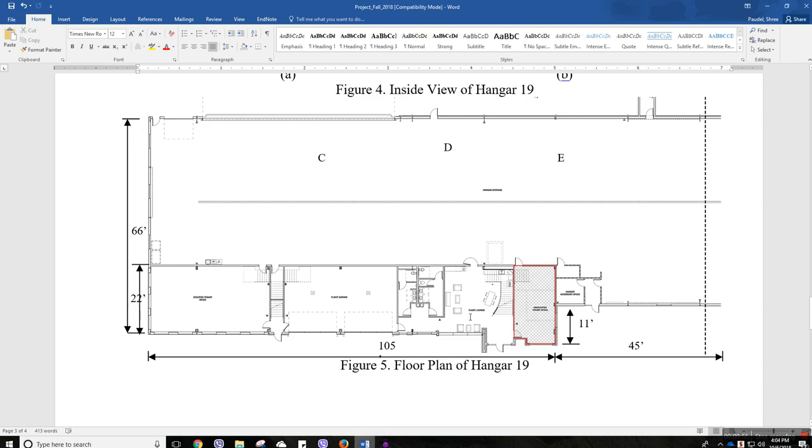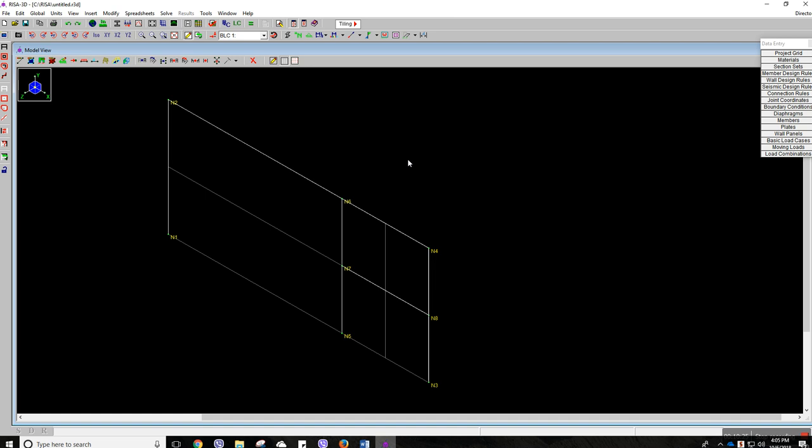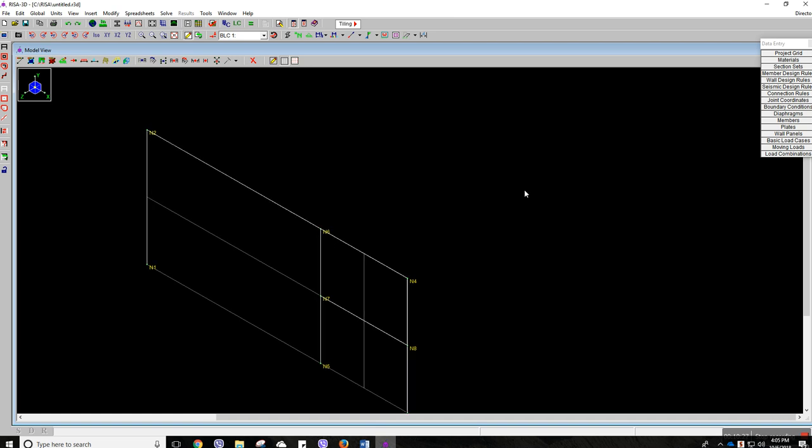So we are going to make the longitudinal axis here. Risa 3D has a very nice application on that one because we can just copy your structure to the other parts. So here, the span is 105 and there are 1, 2, 3, 4, 5 and 6. There are 6 spans, like there are the columns in the middle. So 105 divided by 6 is 17.5. So let's go and copy these structures at 17.5.